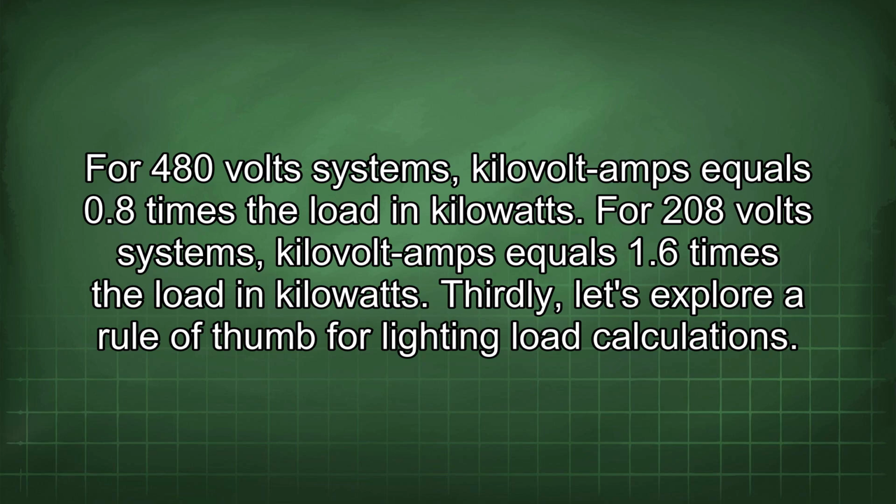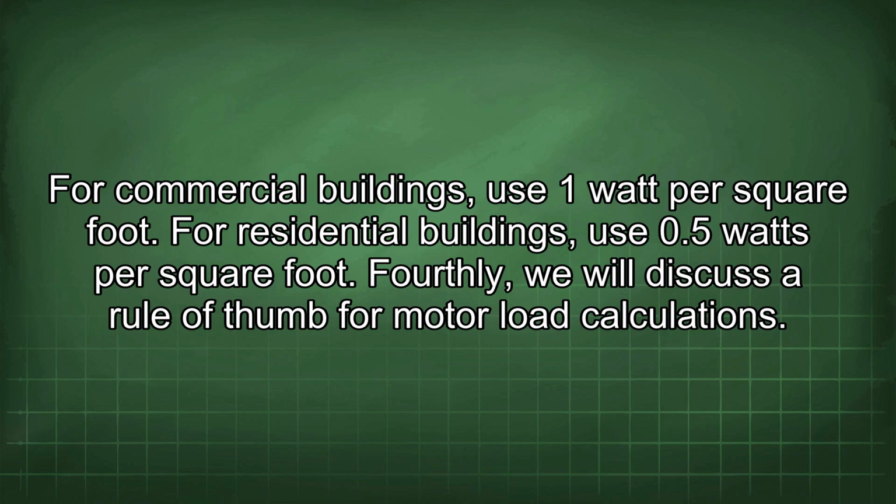Thirdly, let's explore a rule of thumb for lighting load calculations. For commercial buildings, use 1 watt per square foot. For residential buildings, use 0.5 watts per square foot.